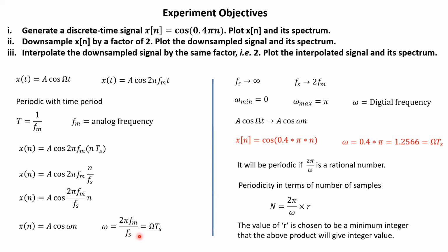If it is less, there will be an aliasing effect, and the spectrum of the signal will be overlapped, and while doing the filtering operation this overlap cannot be avoided. Therefore we cannot reconstruct the signal, and therefore Fs must be greater than or equal to 2 fm. Theoretically, the maximum value of Fs can be infinity.